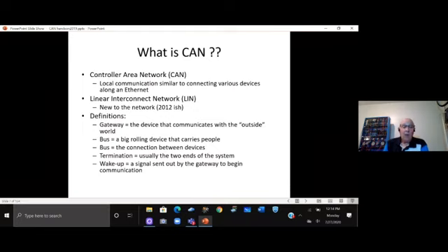Okay? When I walk up to my car or you walk up to your car with the key fob in hand and you unlock the car, as soon as you hit that unlock button, a signal goes into the vehicle, into a module which is awake. And that module then sends a signal to the gateway, and then the gateway wakes up the entire car. So now all the modules wake up, and that wake up signal is something, if you can demonstrate it, it makes a lot of sense to students, and I'll show you how we can do that using a ConsuLab trainer here. But that wake up signal is absolutely imperative.